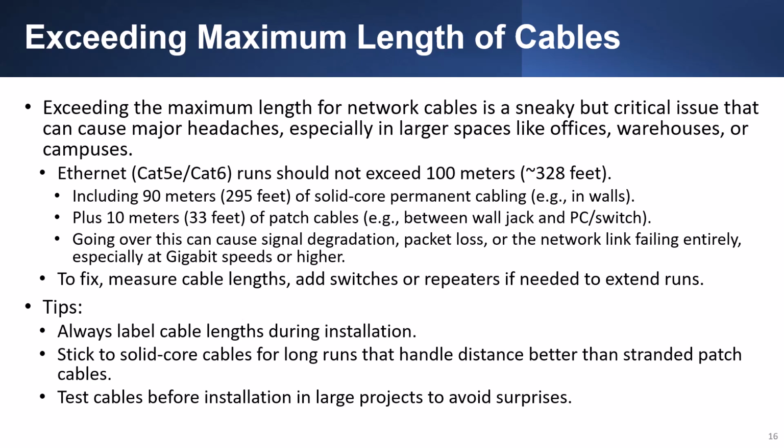Tips: always label cable lengths during installation. Stick to solid core cables for long runs, as they handle distance better than the stranded patch cables. Test cables before installation in large projects to avoid surprises.